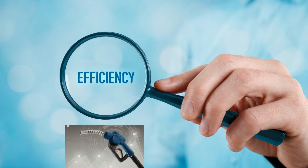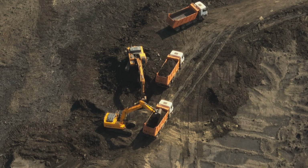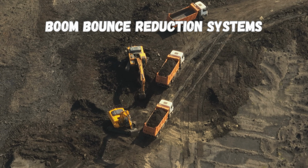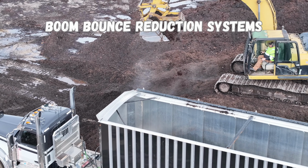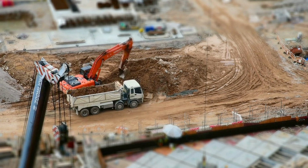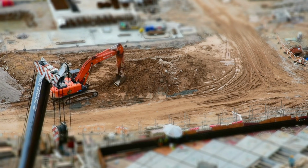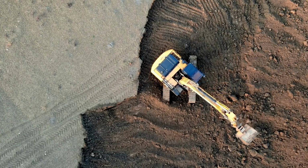Advanced excavators also incorporate several dynamic control features designed to improve machine stability and operational precision. For example, boom bounce reduction systems minimize oscillations that occur when the boom is raised or lowered rapidly, especially when carrying heavy loads. These systems use sensor feedback and hydraulic damping control to counteract oscillatory motion in the boom structure.